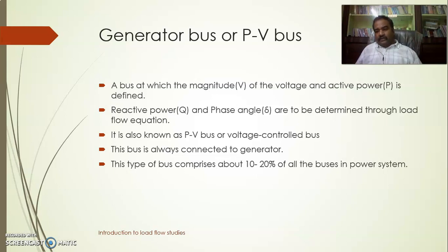Now, whenever we are doing a load flow study, as I have already stated, the primary constraint is that power generation is equal to demand plus losses. So our major concern is to satisfy that constraint, but doing this is a tedious task. So what we will do is start with generation equal to demand, and then include the losses at the end.